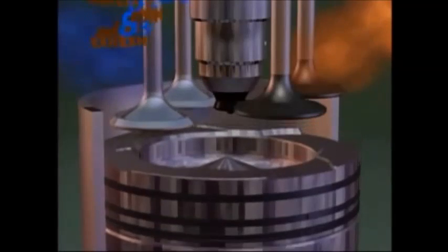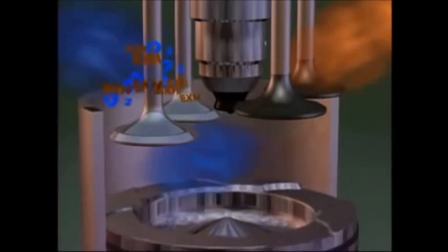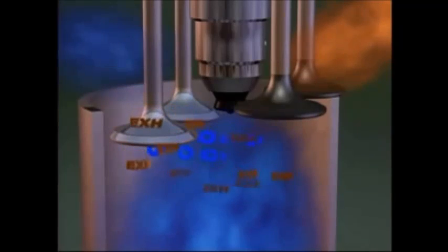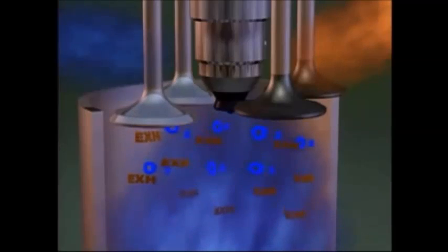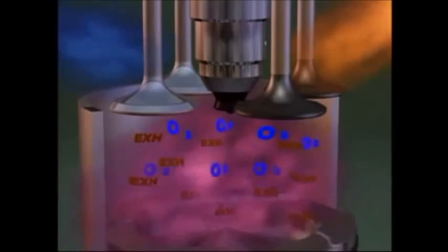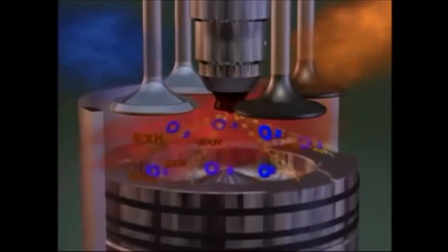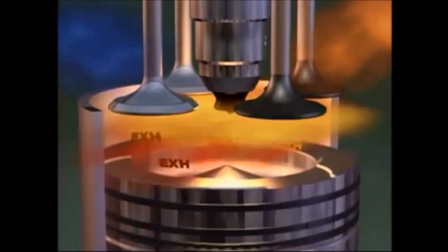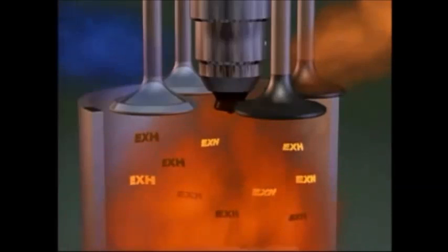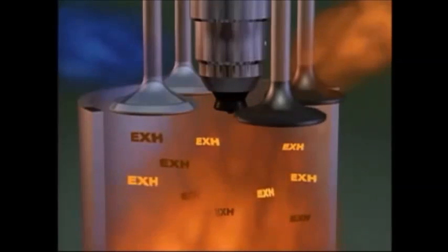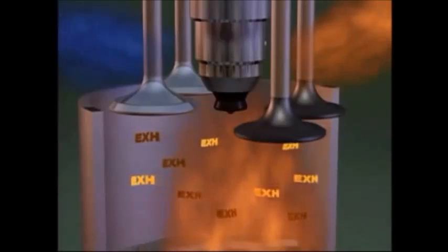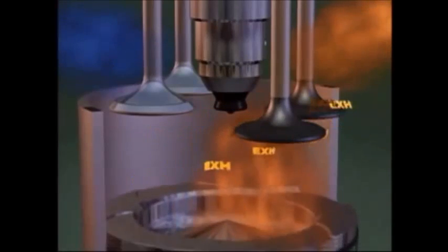The mixture of recirculated exhaust gas and fresh intake air is referred to as the charge air. The extra exhaust gas in the charge air is inert. This means that it has virtually no oxygen in it, therefore it will not support combustion. Also, some of the heat energy during combustion is absorbed by the inert exhaust gas instead of the fresh air, thereby reducing peak combustion temperature. This reduces the formation of NOx while minimizing the use of retarded timing.